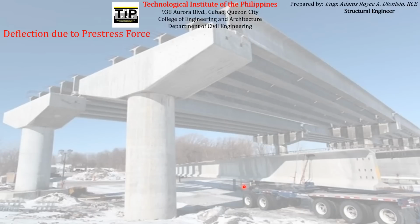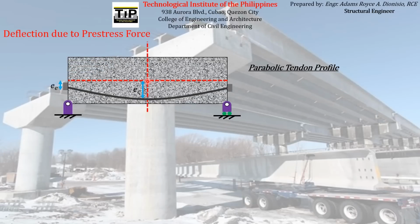Additional formulas for finding the deflection due to prestress force. The formulas that I will enumerate now are general formulas, so you can actually derive the formulas that we have shown a while ago using these. Say for example, for a prestressed concrete beam with parabolic tendon profile with an eccentricity at the ends not equal to 0, meaning the location of the tendon at the supports does not coincide with the neutral axis of the concrete beam, there is an eccentricity at the end supports as well as at the midspan.